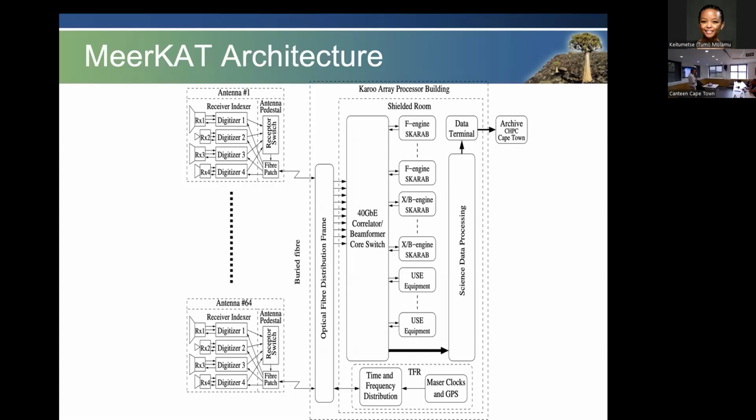And these days, we digitize that signal immediately. We don't even put it through a mixer or anything. We just say, give me that signal, and I'll make it into digits. That's not going to be true for the SKA anymore, because at the higher frequencies we are going to have a heterodyne stage, which moves things down to lower frequencies, because we realized that it was just one step of hubris too big to digitize high frequency signals. Even though you can do it, the A to D converters are not that great. But basically, you digitize the signal as quickly as you can, right there up on the feed, because a digital signal doesn't rot.